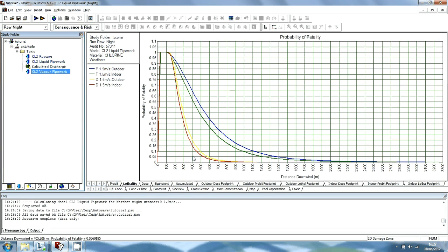We will now define 3 flammable releases. There is a propane sphere at the far north of the site. The propane sphere has the same dimensions as the chlorine sphere and the same design of pipework, and is also operating under saturated conditions at atmospheric temperature. When setting the input data, you can define the rupture and the 2 pipework failures by copying the 3 toxic models and simply changing the selection of discharge material and the eastern coordinate as shown.